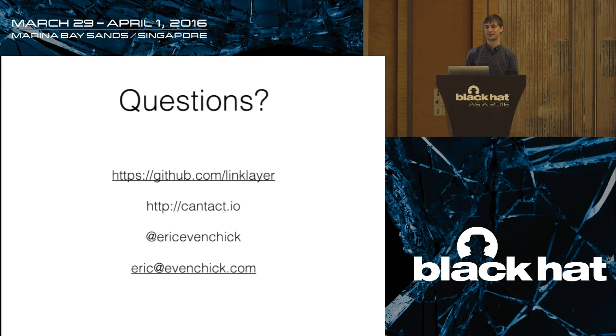And then other things are pretending to be a vehicle for the purposes of reverse engineering diagnostics tools. So I use the example here of, send a seed, which you've chosen. It's really a chosen plaintext attack in this case. You're choosing what you want to have them encrypt. And they'll send back that valid key.